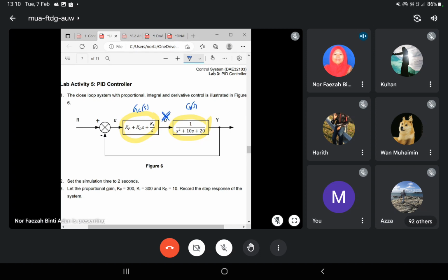And when you have multiplied, what is the next thing you have to do? I don't want to call it G(s), I'll call it G1(s). Like we did in the lab, Gc(s) multiplied by G1(s), you get G(s). Then to find the transfer function, use the closed loop equation G(s) over 1 plus H(s)G(s). Once you have this equation, whatever you want to do, finding poles or zeros, you can.